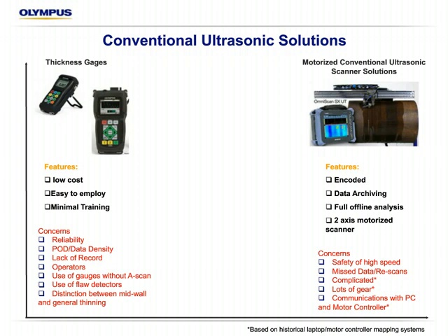Also, the ability to miss data. We'll look at this a little bit further about the typical sensor used in conventional ultrasonic mapping systems, but it's usually a dual crystal, very small, about 0.187 inch. So imagine moving at very high speeds. Our in-service conditions aren't always the greatest. You have rough walls. You could possibly lose coupling or fall into an actual outside surface rough area or OD corrosion that could cause a data point to actually be missed.